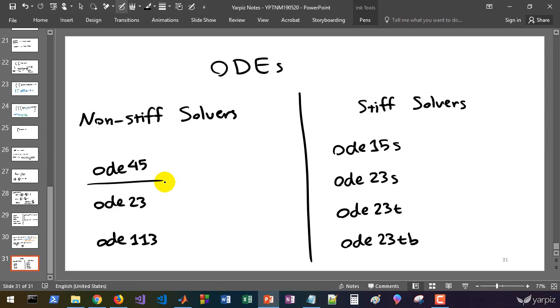Generally, ODE45 is our first method to try, and most of the time it's useful and it is capable of solving most models in ODE form. However, in the presence of moderate stiffness or for problems and models with crude tolerances, ODE23 will be better than ODE45, and for models with stringent error tolerances or for models which are computationally expensive to evaluate, ODE113 will be a best choice.